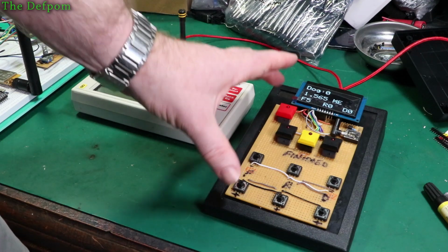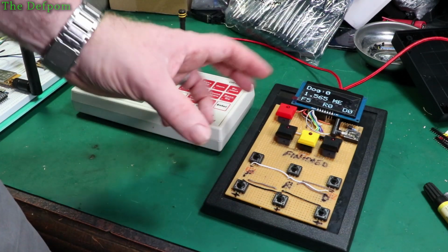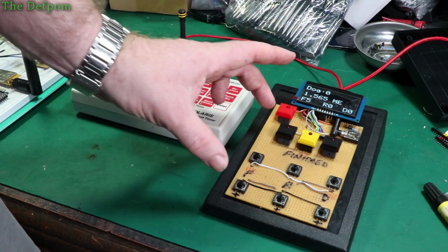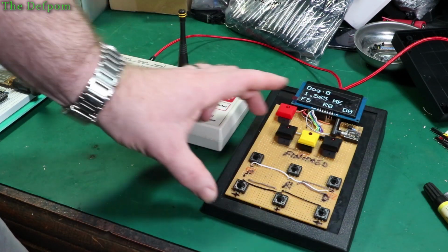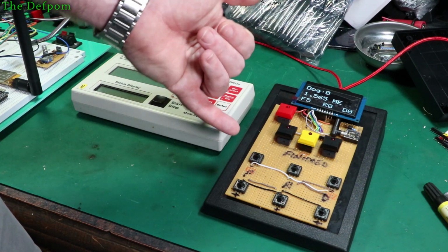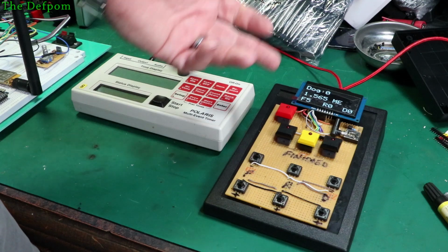I've ordered a board because of the size of this board here, and my restriction with Eagle only being able to do 80 by 100mm or something like that. I've had to do this in 2 boards, so I've got one board which has all the buttons on it, those 9 buttons. And I've got another board which is going to be a controller, so that's got the display, the ESP32, the LoRa, the SD card, and stuff like that on it.